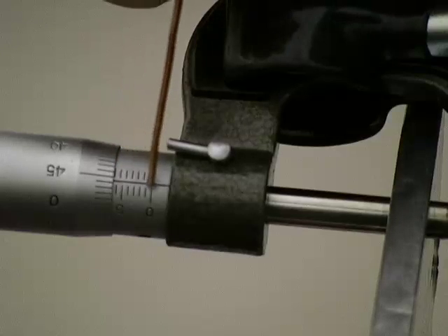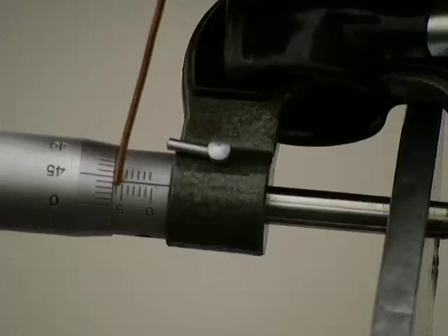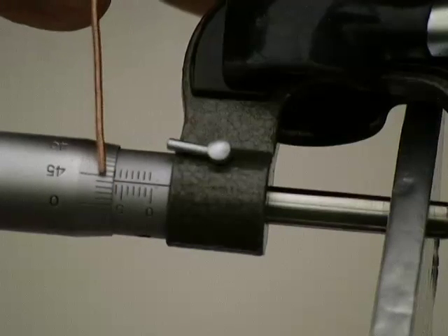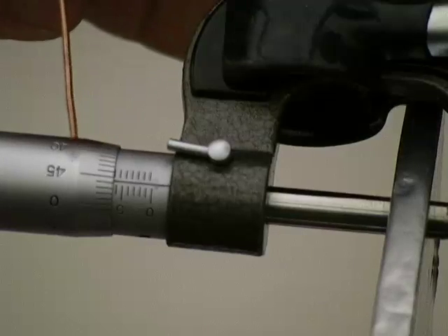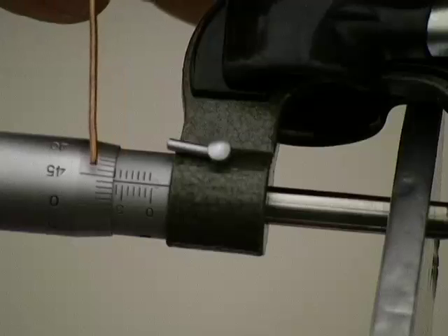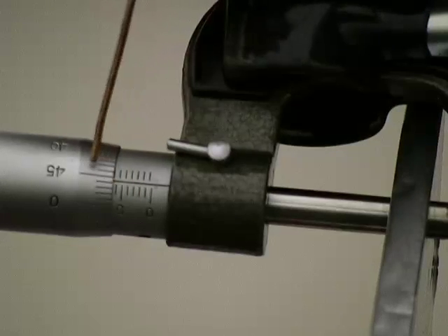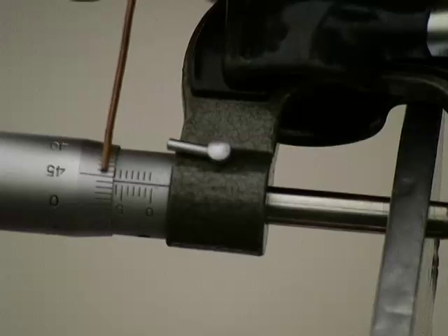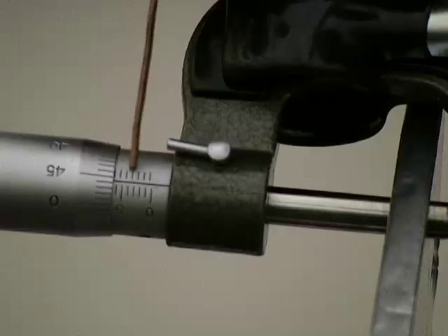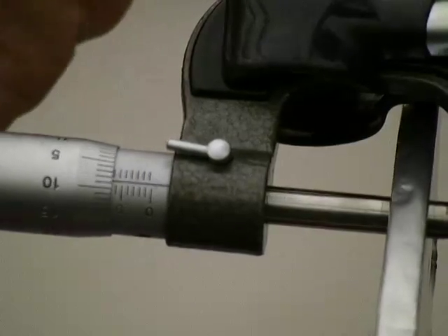Well, I don't think there is a 0.5 there. This is up to 6. I can read up to 6 millimeter, and the round scale reading is 45, and multiply that with 0.01, the least count, and so this reading is now 6.45 millimeter. You see that? 6.45 millimeter.